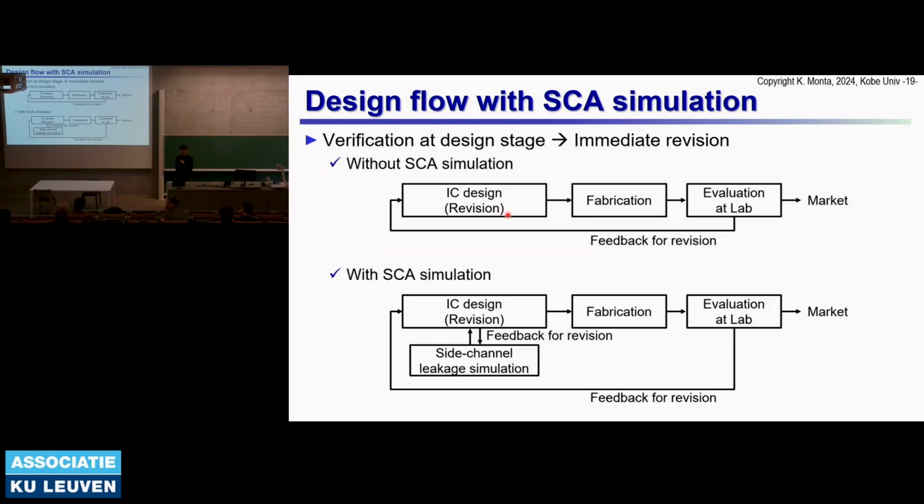However, if we have side channel analysis simulation, we can do the evaluation at the IC design stage and immediately give feedback to the IC design. It makes the process shorter and less expensive. Of course, it is needed to evaluate at the lab at the last stage, but you can do the respin at this design stage. This is an important point of side channel analysis simulation.